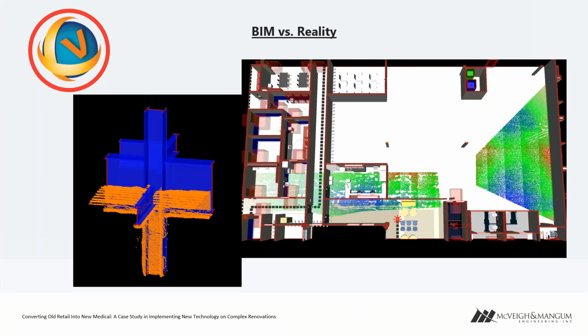The other part of it, this is the ambulatory surgery part, was that we started looking at floor flatness. We were able to run the Rhythm side of ClearEdge and see our floor flatness study across how it was working, and really the areas that we needed to go back and look at. As you can see on the right, we did the heat map and overlaid it onto our floor plan, which allowed us to analyze it. That was just one piece, which is why you can only see certain portions, but we are analyzing certain areas for certain reasons.